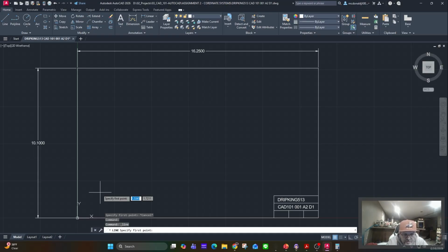So I'm going to go ahead and start this at 2, 2. So I'm just typing 2. I hit tab, typed in 2, hit tab again. Both have little locks, so we know that it likes it, or it's got it in place. We'll go ahead and press enter. Point number 1 has now been made.